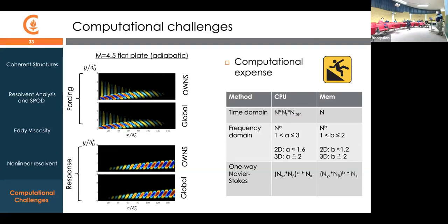Can I just ask, an algorithmic point here? When you process the data, you do a Fourier transform in time, and then you take the fluctuations and find the two-point correlations, and if the leading eigenvalue of that is what you're calling a coherent structure. Yeah, that's exactly right. You don't just compute the Fourier transform; you do something clever, you have to average. You're taking a fluctuation at one given frequency and seeing how it's correlated with every other. You do everything in the frequency domain, so it's cross-spectral density, but in the time domain this would be the correlation.